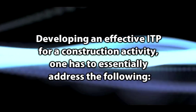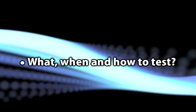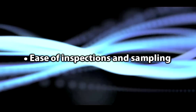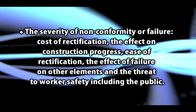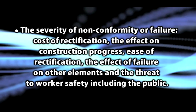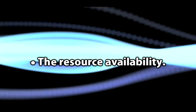On reviewing the above, it is noted that when developing an effective ITP for construction activity, one has to essentially address the following: what, when, and how to test, the type of construction activity and its complexity, ease of inspections and sampling, the severity of nonconformity or failure, cost of rectification, the effect on construction progress, ease of rectification, the effect of failure on other elements, and the threat to worker safety, including the public. And finally, the resource availability.